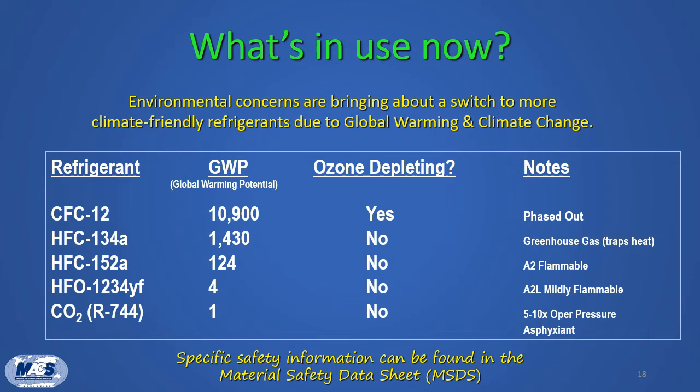We also have 2 other refrigerants listed here, and we'll first talk about R152A. Since the EU, the European Union, has set a GWP limit of 150, this allows the use of R152A as a mobile AC refrigerant. The US EPA has also allowed R152A, but with certain use conditions due to its flammability, which is listed as A2. It must be used in what's called an SLMAC, or a secondary loop mobile AC system, and while not currently in production, it is being developed by several companies.